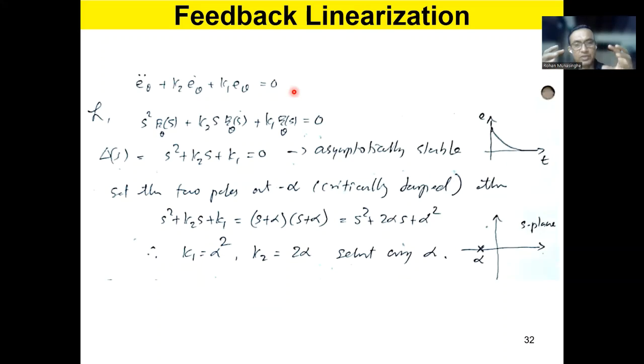And this is very interesting because when you see the error dynamics, remember the error dynamics we discussed some time back. When you have the plant with this kind of error dynamics, you know that the plant is asymptotically stable, which means you can stabilize a plant. So if you start with some error initially, it will go down to 0 like that.